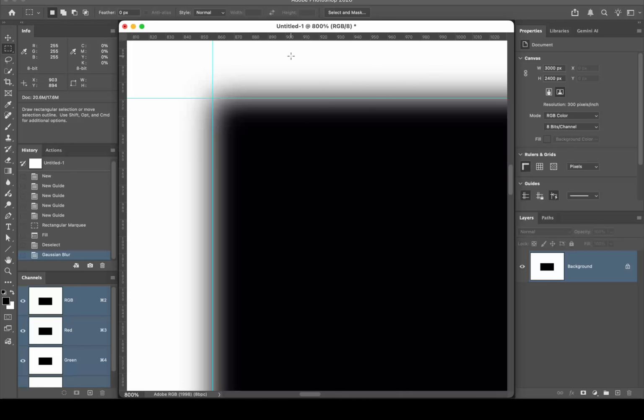Anybody not? Stop me next time. My box doesn't fit. Okay, that's because you still haven't changed your feathering either. It's still at 20. Hit Command D to deselect, and then change that to 0. Now try and click and drag out. And you're also set to ratio. That should be normal. Command D to deselect. All these things are sticky, so you need to change them back to their defaults, and now it'll work. So go ahead and try it.